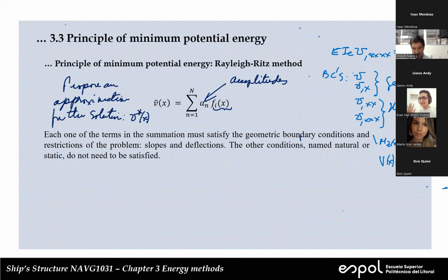The shear force is 0 and the other is that the moment is also 0. Exactly. Are they natural or geometric boundary conditions? Natural. Yes, both are natural boundary conditions.